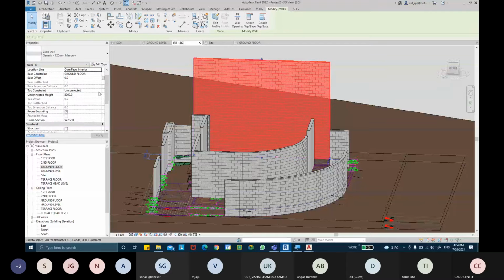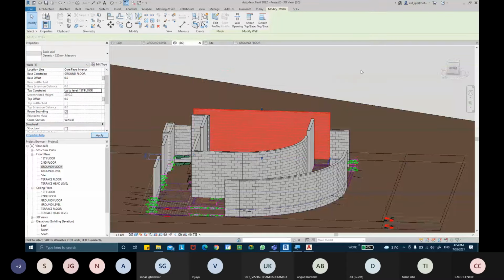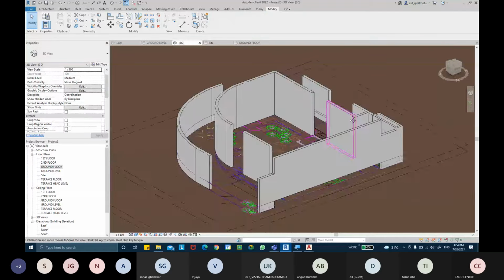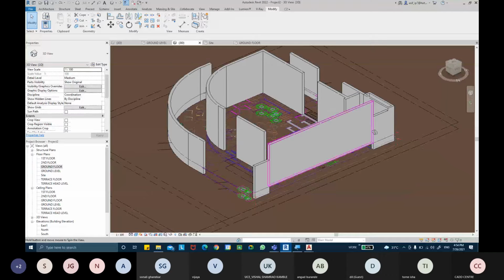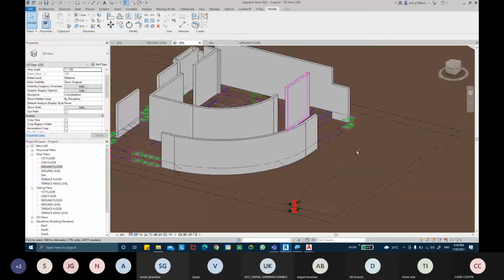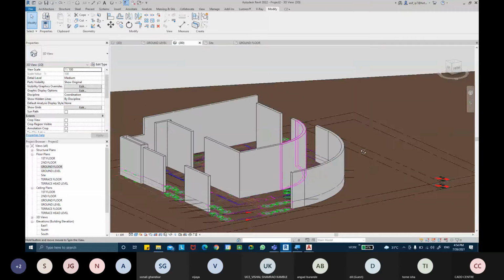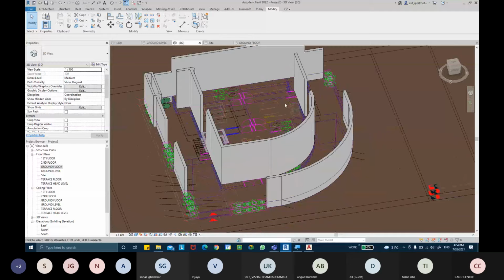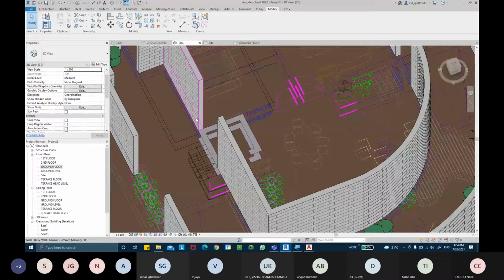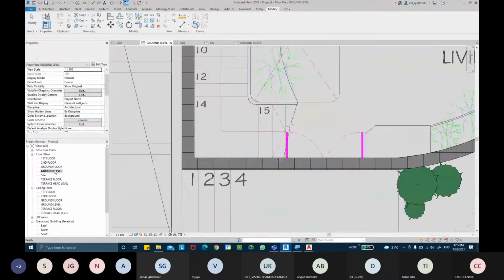We can take this wall also till the first level. So there will be the plinth at the bottom. The plinth beam will be coming in the bottom, running all the way, and on that we'll be having the entire floor plans in order. The left wall can be the core wall, so that we can again come from the ground level.